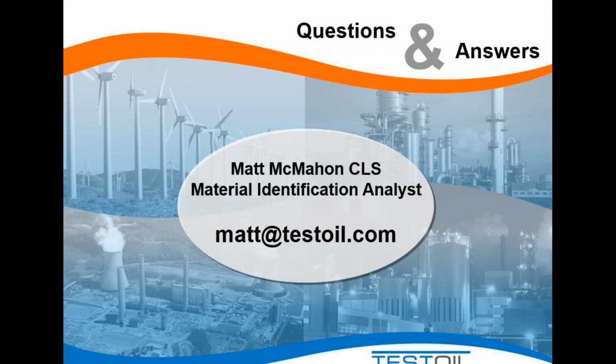I bring that up a lot of times in my training sessions: we don't want to get locked down to just a single source for some of these metals. An example that I use a lot is aluminum. If we take a look at the report, aluminum is generally regarded as a wear metal, and yet we know that it could be contamination.